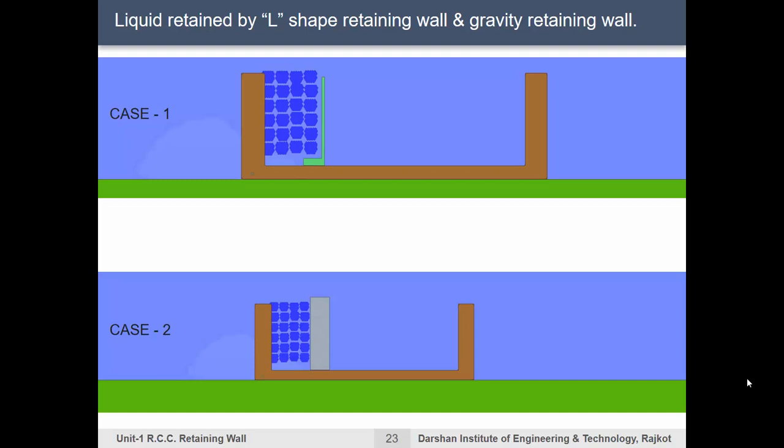The reason is the pressurized water in the dam may seep under the base of the retaining wall, and if it does, the resultant upward water pressure on the bottom of the retaining wall can generate an additional overturning moment and make the dam overturn. The projected leg of an L-shaped retaining wall will generate a large lever arm, resulting in large overturning moments due to the vertical seepage pressure, in addition to the horizontal pressure generated due to the vertical column of water. Let's see this in our simulation.